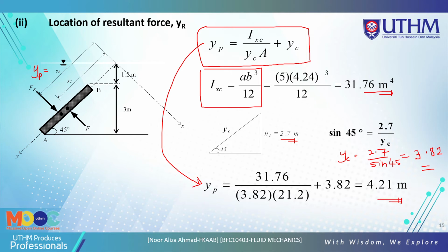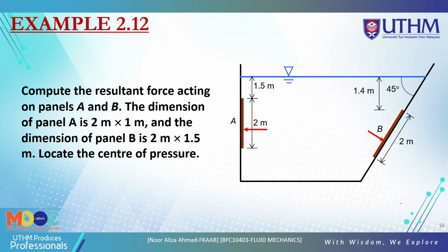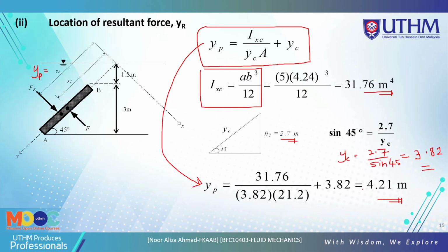The hydrostatic force is more complicated, so you must understand and calculate step by step. So until this part, you can understand: find the magnitude, find the hydrostatic force, and then find the location of the resultant force or hydrostatic force, YP or YR. This is the location of the hydrostatic force that you must calculate.